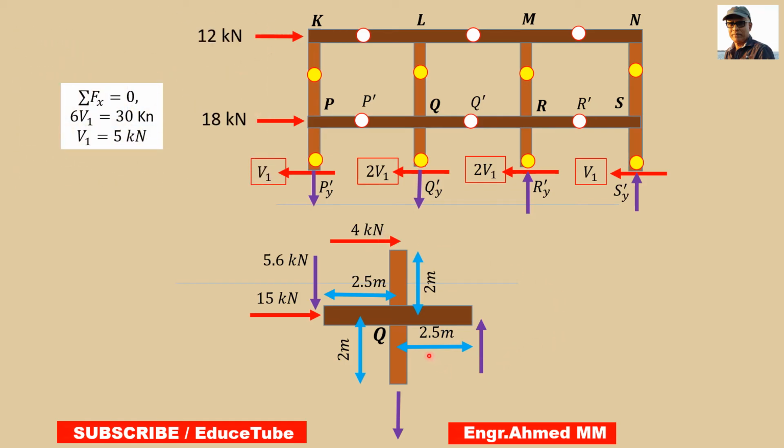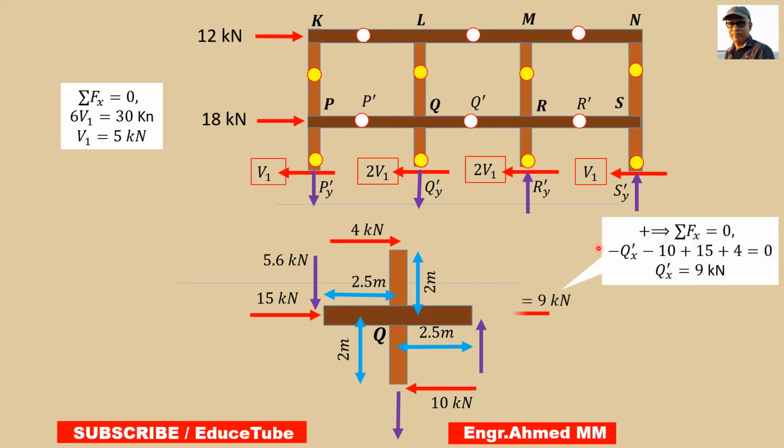Now, like other segments, we can put the value here, because easily we can take it from this value 2V1. So V1 means 5, so 2V1 means it will be 10. So easily we can write here 10. Now summing horizontal forces, we can find Q prime x. So minus Q prime x, minus 10, plus 15, plus 4. Easily we can find Q prime x equal to 9.